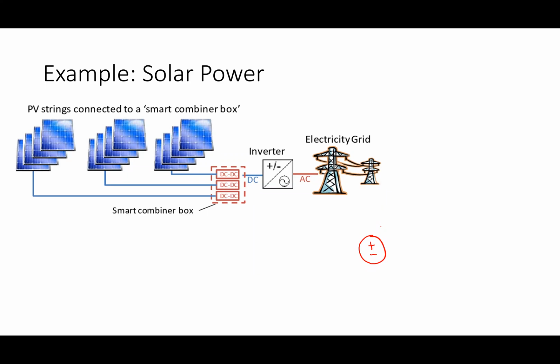What would be from a circuit, if I looked at the wall outlet? Going into the wall outlet, what does it look like? What's the circuit model? I can make a Thevenin equivalent for it, right? And so there's going to be a VOC, and there's going to be an impedance, ZEQ. That's the grid right there. Grid's a very complicated place, but it can be made that simple.